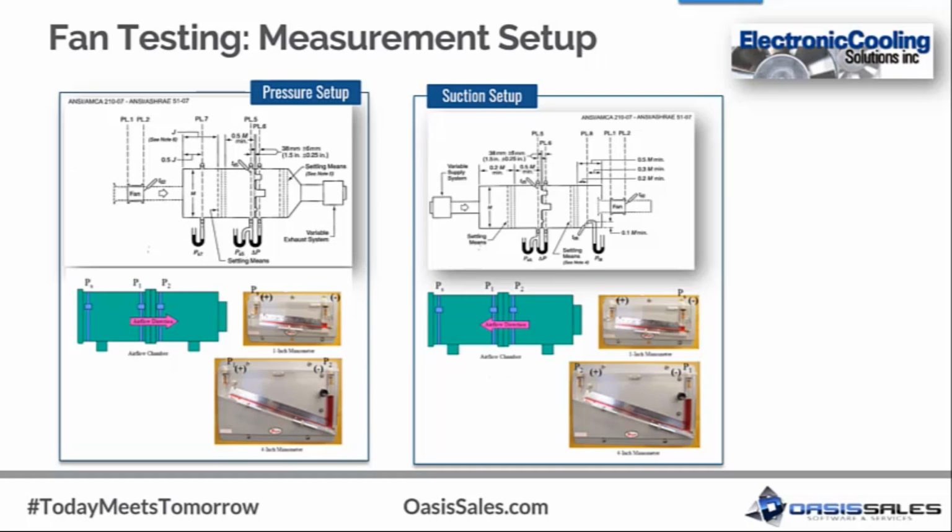Pressure at each cross-section is measured by multiple static pressure ports connected by a tube. This averages fluctuations measured at a cross-section. Static pressure is measured at sections shown as PL7. Differential pressure across the nozzle is taken at sections PL5 and PL6. Bernoulli's equation coupled with the continuity equation is used to compute the airflow that passes through the nozzle. This is easily calculated using the Excel sheet that is provided along with the airflow chambers.